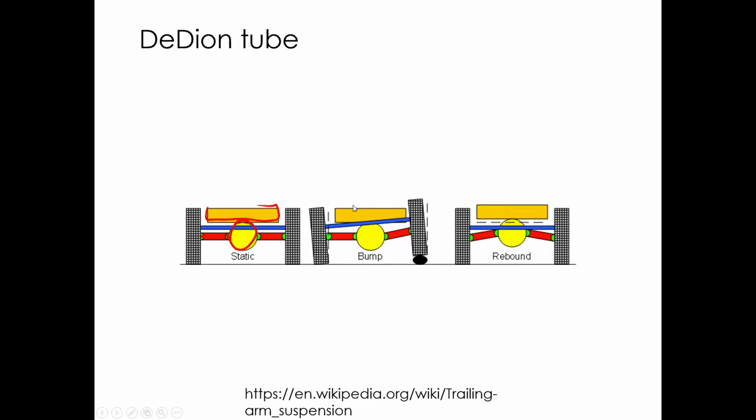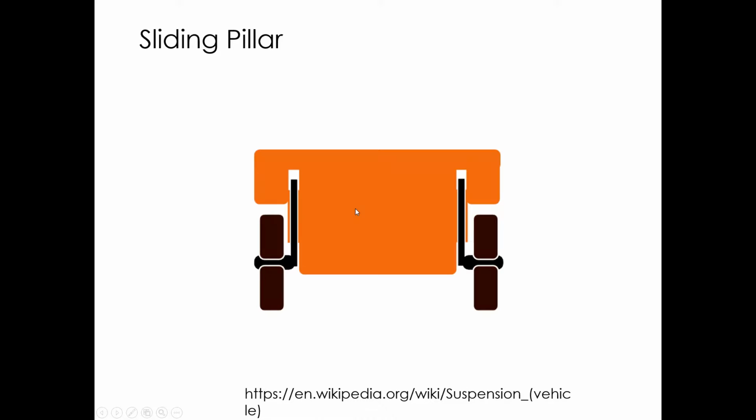That's called unsprung weight. There's the sprung weight, which is the weight that's on the springs of the suspension. And there's unsprung weight, which is like the wheels and tires and part of the drivetrain that isn't controlled by the springs and the dampers on the car. And you ideally want as little unsprung mass as possible, just because you can control the motion of the sprung mass with your springs and dampers.